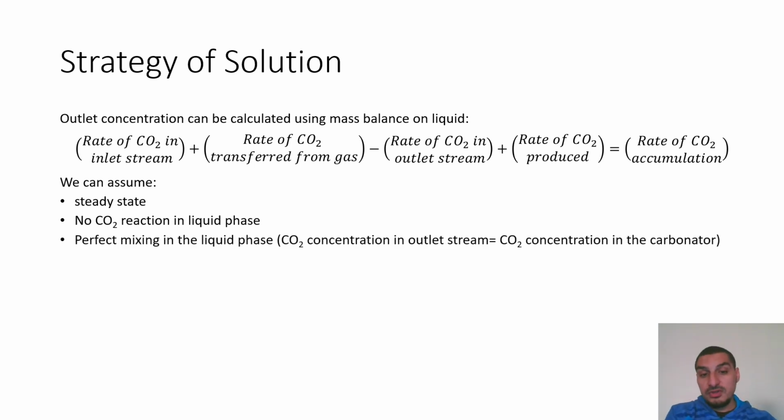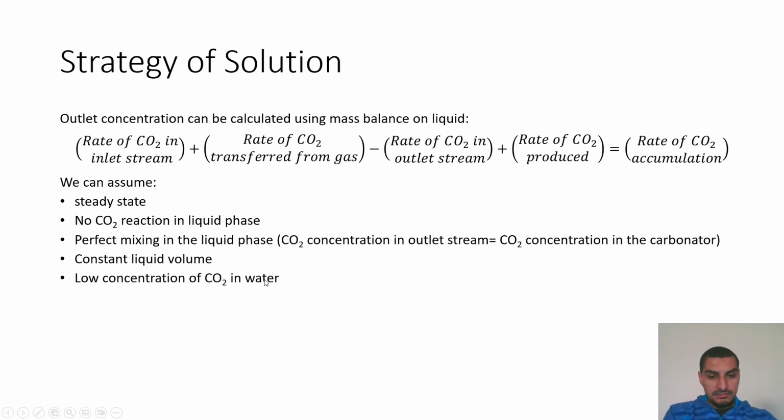We will put some assumptions here that we have steady state, we have no reaction, and as we said, there is perfect mixing, which means that the concentration of carbon dioxide in the outlet stream equals the concentration inside the carbonator or inside the tank. The liquid volume is constant, the concentration of carbon dioxide in water is very low, and we will see why these two are important for us. But this will be later.